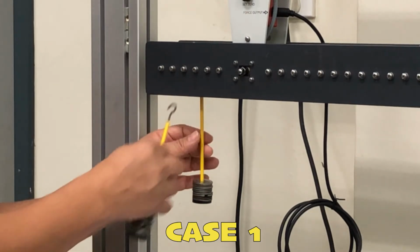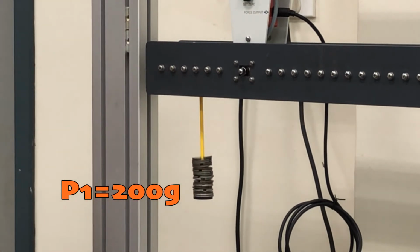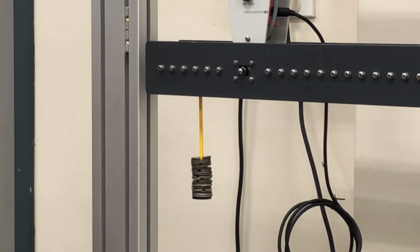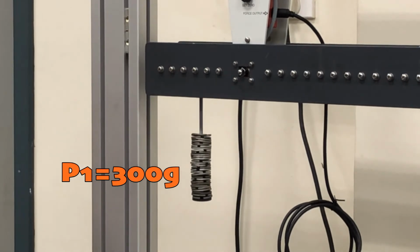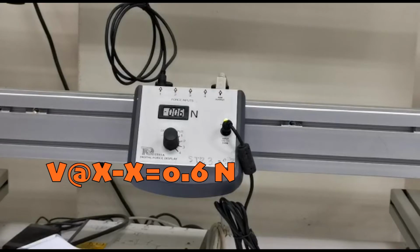For the second trial in case 1, it will be 200 grams, and the same procedure is repeated. The digital display shows the value is minus 0.4 Newton, and the value of the shear at cross-section is 0.4. The third trial is when P is equal to 300, and we have Vxx equal to 0.6 Newton.